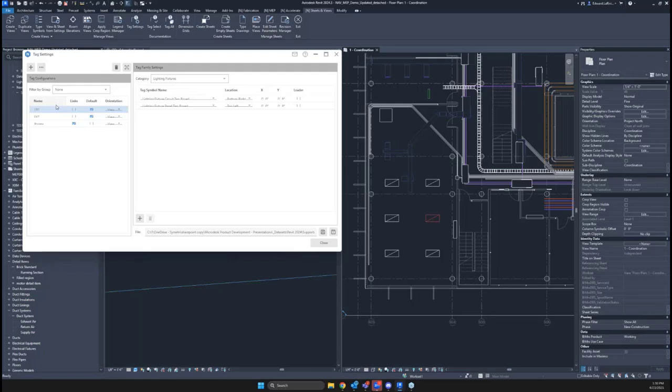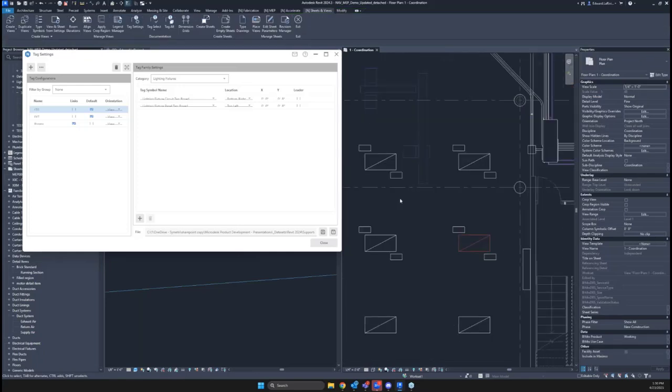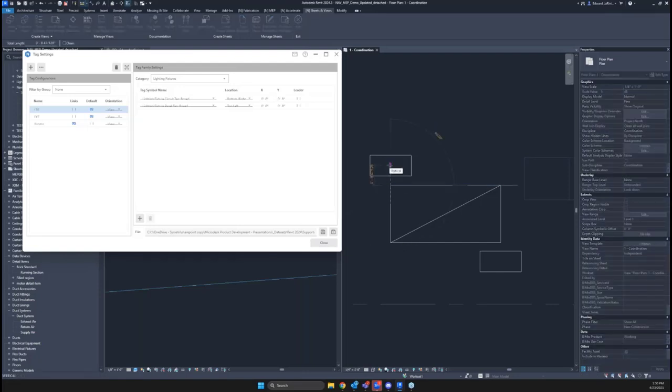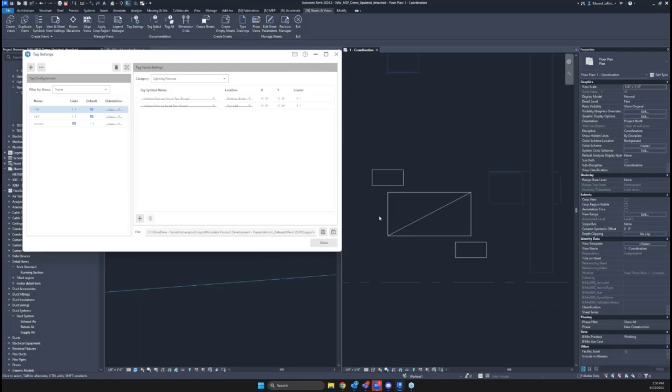All right, I do apologize here, but I can tell you exactly what's happening, and you'll see it in 2 seconds. As I click that lighting and we look on the right, you'll see I'm actually calling out 2 different tags, a circuit tag and a panel tag. I'm asking for them to be placed in 2 different locations, the bottom right and the top left. And then I'm asking them to have an offset from the element of 8 inches. What does that look like? It looks like a tag in the top left and the bottom right. And it looks like that tag has been placed 8 inches off the bounding box of that element.